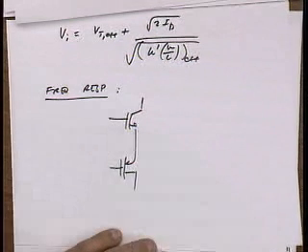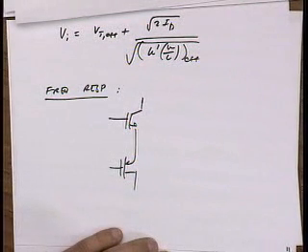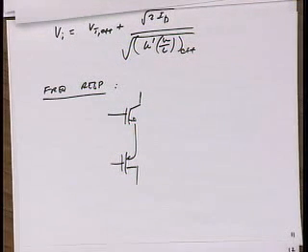Well, remember, this is a differential circuit. Did someone have an idea? Yeah. You size it for equal VDSATs so the swing on both sides is equal. How does that help? So your excursion out both ways, it linearizes it. I don't know, equal VDSATs. Okay, but we're talking about frequency response, right? How does that help frequency response? You're actually onto something. Why does that help frequency response?